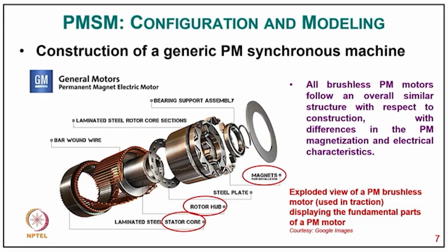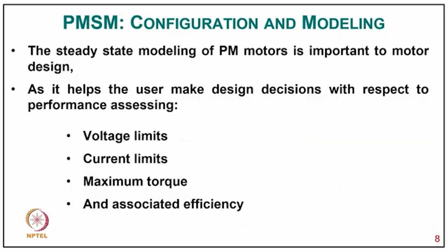So, all brushless PM motors follow an overall similar structure with respect to the construction, with differences in the permanent magnetization and electrical characteristics. Here is a very interesting configuration where saliency torque is reasonable in addition to permanent magnet torque. Now, the steady state modeling of permanent magnet motors is important to motor design, and it helps the user make design decisions with respect to performance assessment like voltage limit, current limits, maximum torque and